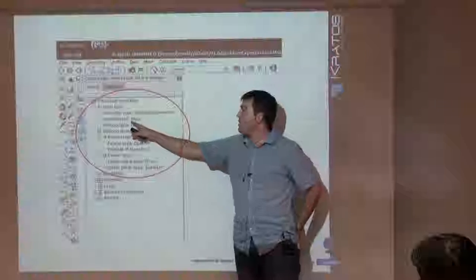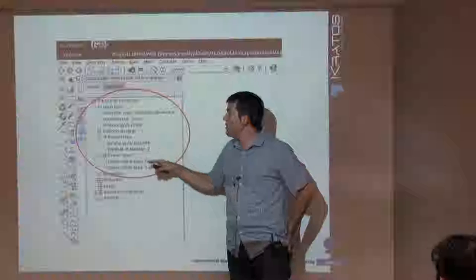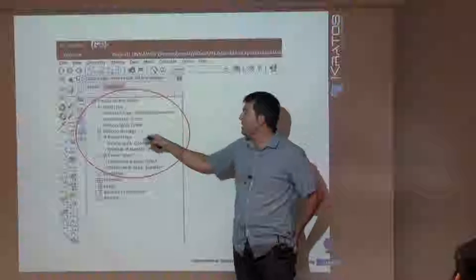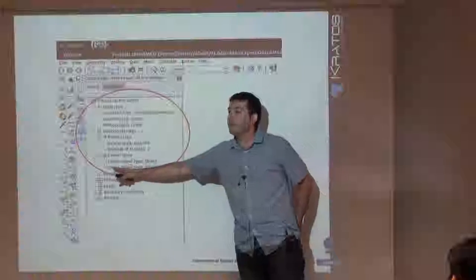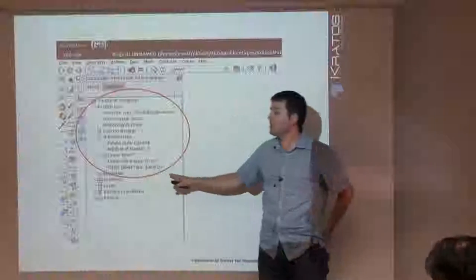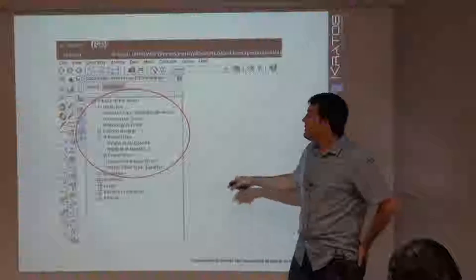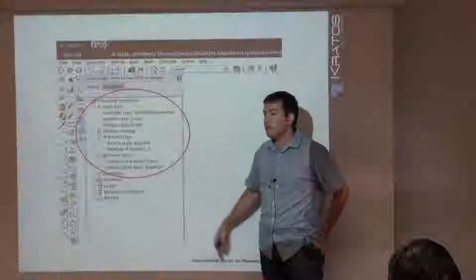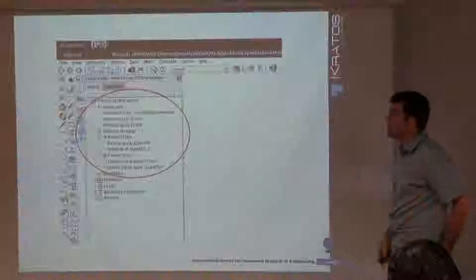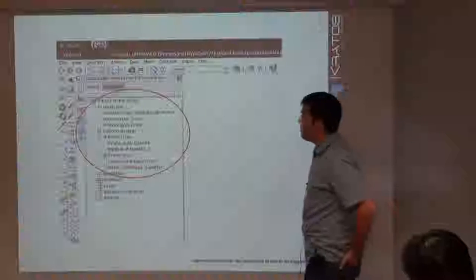With analysis type we are going to control which is the solution solver that we are going to use. If we select linear, automatically we have here the linear solver. If we select non-linear, we will have here just iterative solver with different type of menus to select which are the convergences for non-linear solver, which type of non-linear solver we want to use.